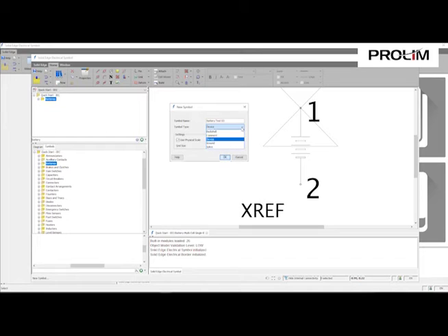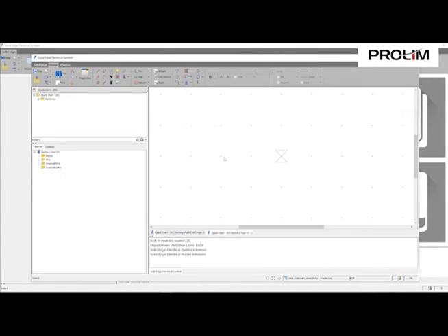And again, we can select what type of symbol it is. So we can do a backshell, a comment, if it's just a comment that we want to be able to bring into a diagram, a device, a ground, or a splice. So let's just say this battery is a device. And again, I can use the physical scale, or I can control it based on the sizing of the layout itself. But I'm going to go ahead and just leave it all as default. Okay. And now I'm in the new symbol generation.